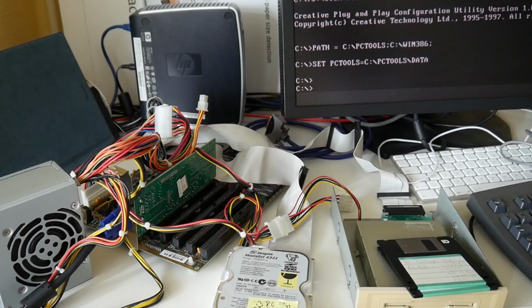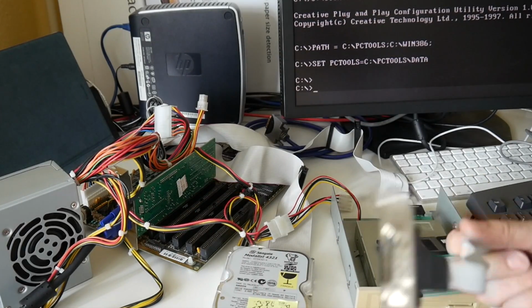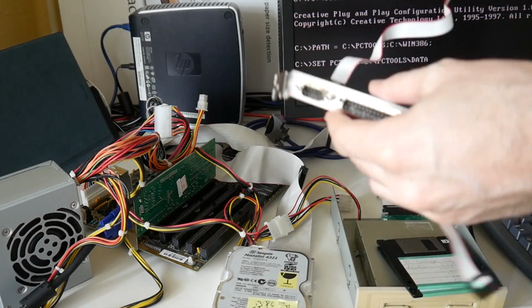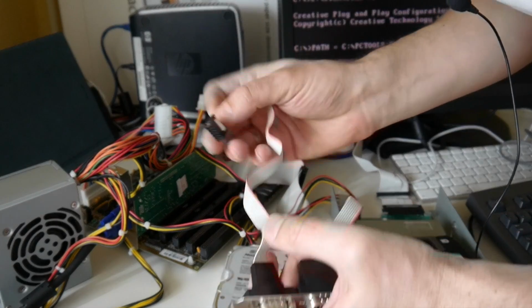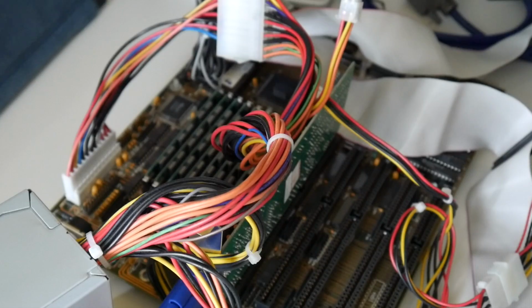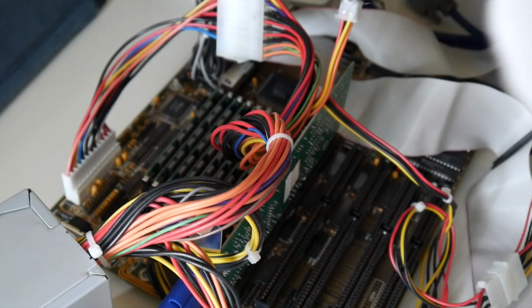Wow. Let's connect the serial I/O slot thing. And of course it's not coded, except the pin 1 thing. And as I said in the initial videos, this is one of those modern 386 boards that have this integrated. On the even older ones you had a separate ISA card with the I/O stuff. And where is pin 1? There is COM, and CN5, CN6.